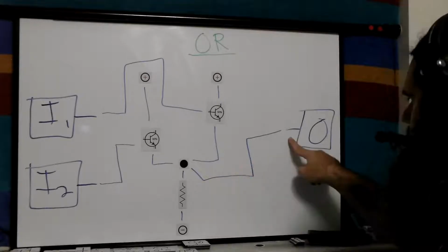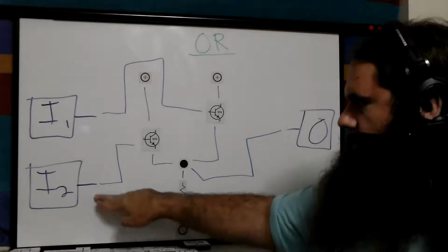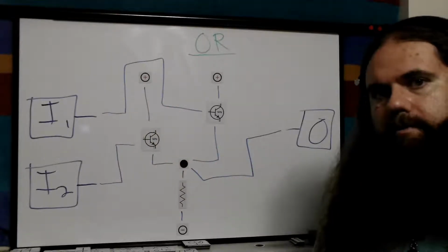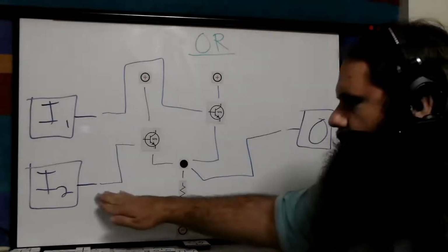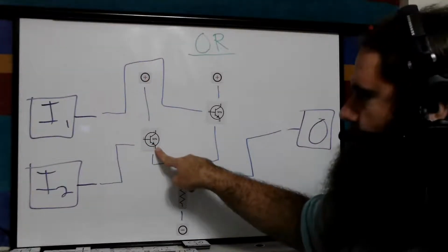What you have is your output connected through a resistor to ground. So this is low, and that is low. Now what if we turn one of them on? Let's turn this one on and leave this one off. So this one's high. High to low, forward biased, conducting.